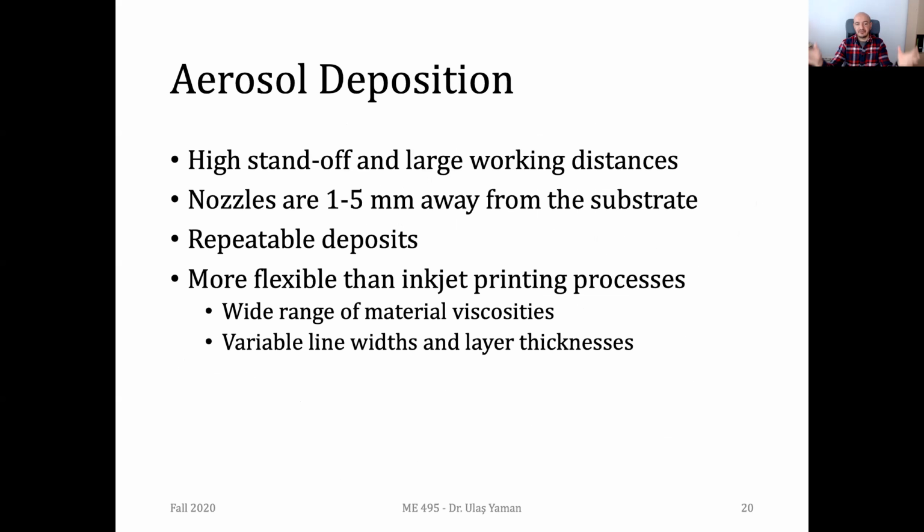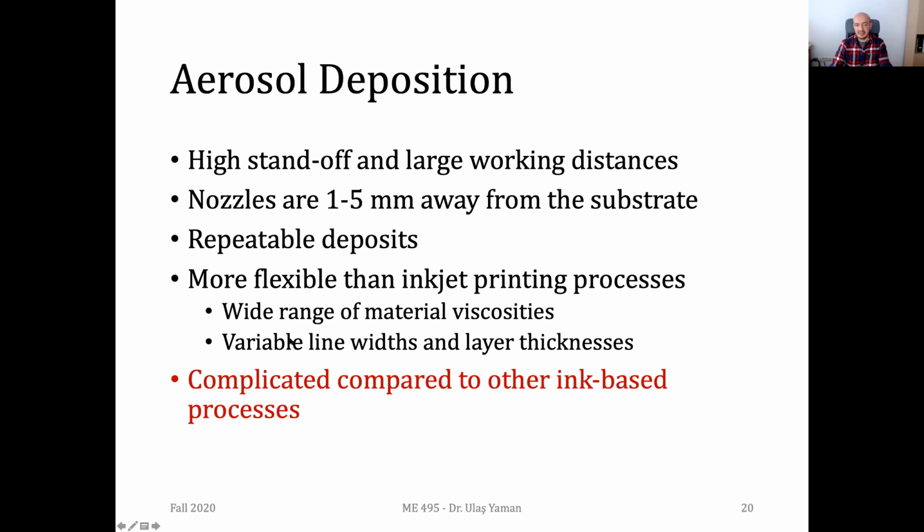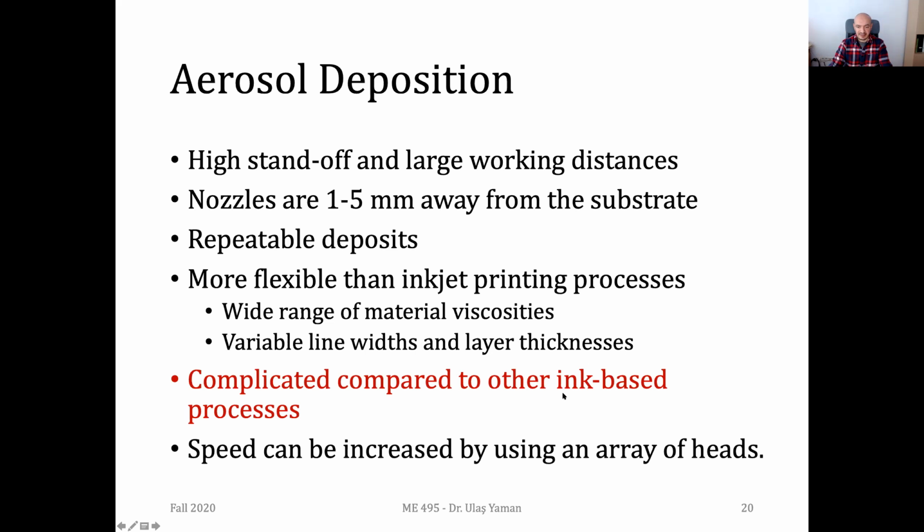You can have different materials in the chamber. They may all be atomized, even with different viscosities. And by modifying the nozzle, you may have different line widths and even different layer thicknesses. But the problem is that the whole machine is quite complicated. It's a bit costlier than the other ink-based systems. If you have, let's say, multiple heads, you can decrease the fabrication time. But again, the cost of the system will increase.